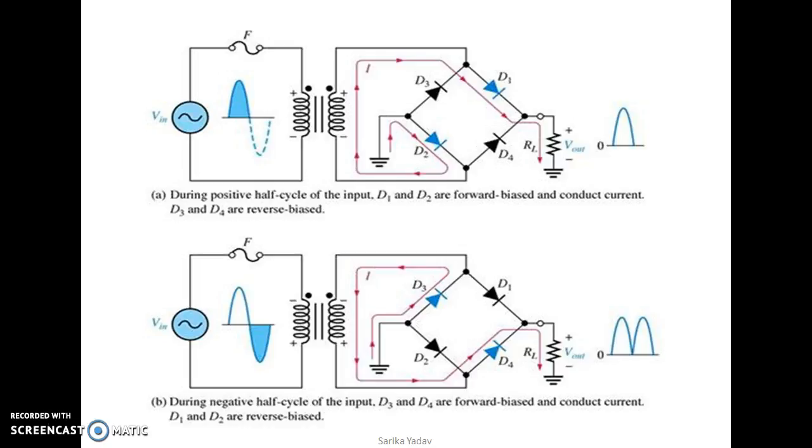Now, as we have got the output at rectifier end, still it is not pure DC. It is called as pulsated DC at the end of the rectifier. To make it pure DC, we need to purify it in a more proper way, and for that we use filters. So I will give you the introduction part of filters in next video.